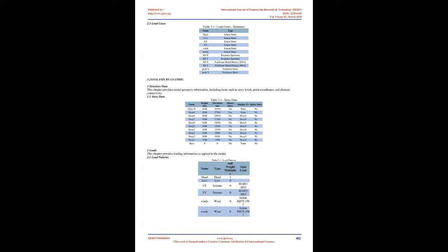It has been concluded that maximum value of story shear was observed for L-shaped plan than rectangular building and C-shaped building. The story drift values in X direction and Y direction increase from top to bottom story in all 3 cases. When earthquake load is applied in Y direction, it was found that irregular plan structure can resist more base shear than rectangular plan structure. Regular building and L-shaped buildings gave good results than C-shaped buildings in all aspects.